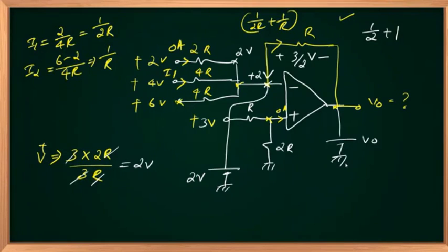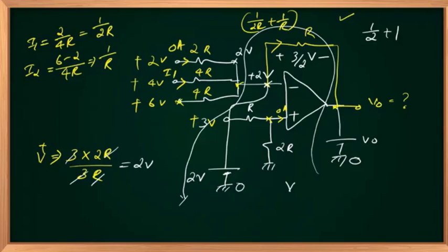Okay, again answers are different, right? Minus 0.5, plus 0.5, let us fix it. Let us write KVL around this group, then the issue can be resolved. Starting from 0, ending at 0. So negative to positive plus V out, negative to positive plus 3 by 2 volts, plus minus minus 2 equal to 0.